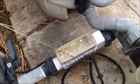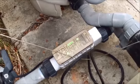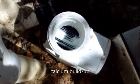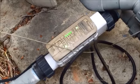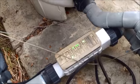And the main problem you're going to have with your salt system is the cell gets calcium buildup depending on how hard your water is. Some cells will tell you when they're dirty, other cells won't. So every 3 months you want to take it apart and inspect it for calcium buildup. If your salt cell has a lot of calcium buildup, the salt chlorinating unit will not work, and no chlorine will be generated at that point.